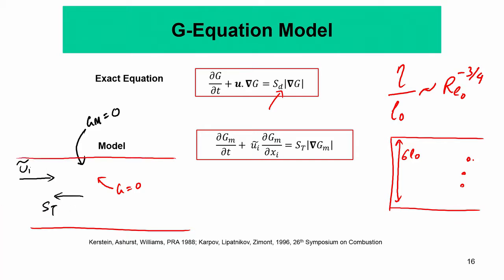So this was what my domain was. This is the instantaneous flame surface, and this is the mean flame surface, which has to be straight because it's statistically planar, and so it now behaves almost like a statistically planar 1D flame, but of course its structure is very much different from the 1D flame because it is averaged.